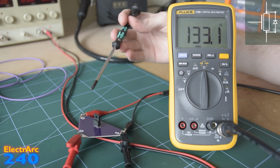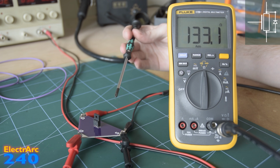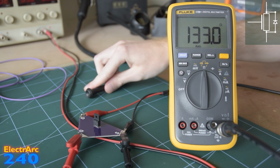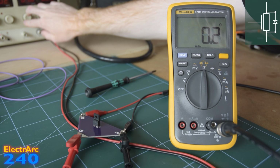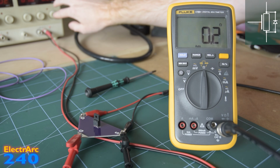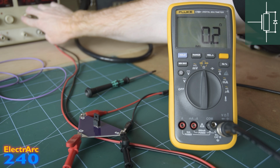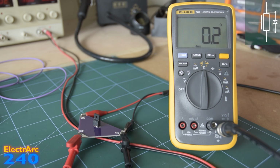So if increasing the voltage between the gate and the source reduces this channel resistance, can't we just keep increasing it? Well, let's see what happens if I do. Right now I've taken it down to 3 volts. Let's have a look. This is at 7 volts, we've got 0.2 ohms. This is at 11 volts, 0.2 ohms. And finally, this is at 18 volts, still 0.2 ohms.